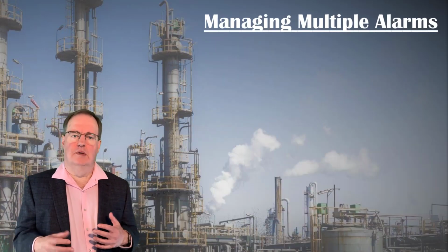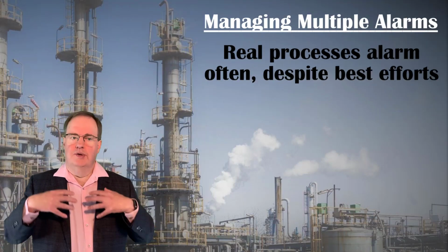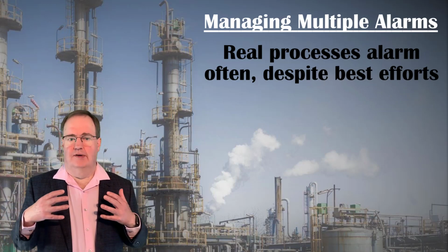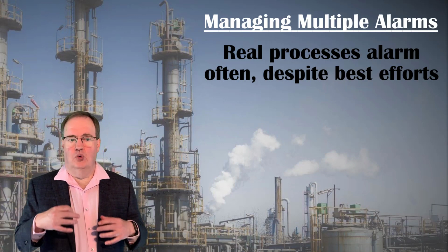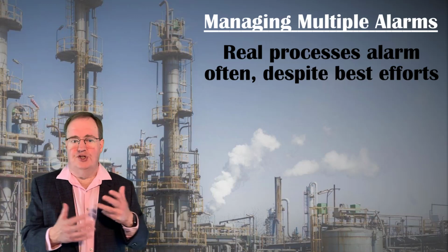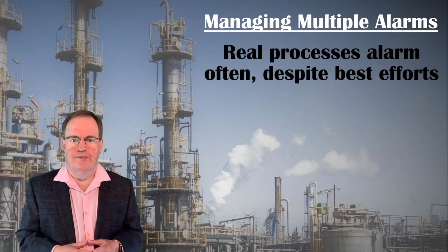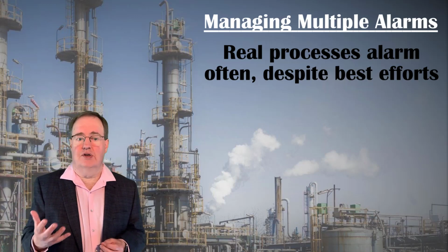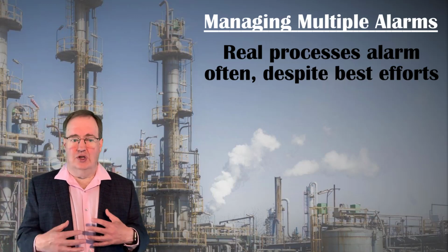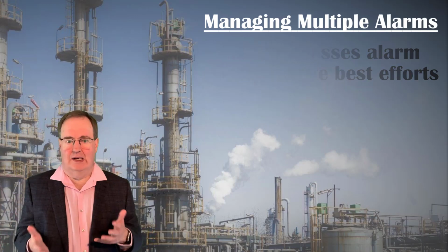Even if we succeed in eliminating most nuisance alarms, operators in a normally running process will often see many alarms in an hour due to normal status alerts of normal changes, sensor noise that quickly reverts to normal, or legitimate deviations that feedback and digital controls cope with automatically, but are nevertheless still alarmed. When something actually goes wrong, often many alarms are triggered simultaneously, because a high temperature can lead to a high pressure or a high level, because everything in a process interacts.